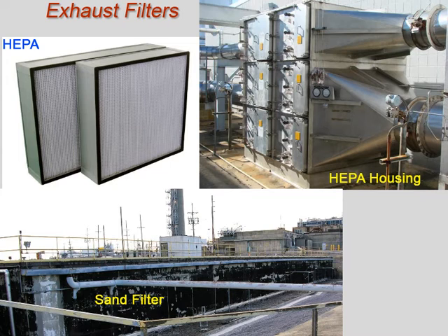HEPA filters are designed to handle any level of contamination. Air that is considered to be less contaminated is passed through a set of HEPA filters. These HEPA filters have an efficiency rating of 99.99% for particle sizes of 0.1 micron and larger.